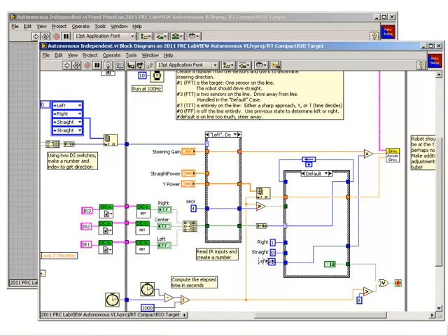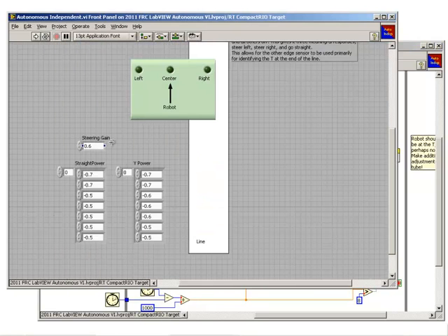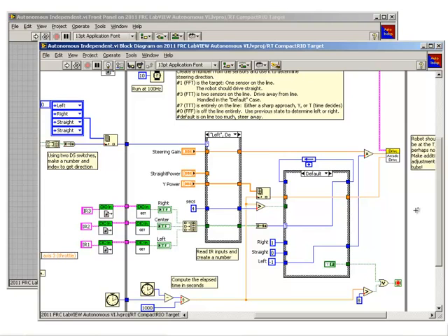Straight has a value of 0, therefore the robot will not turn at all. The degree of the turn will be determined by the value of the steering gain constant. A higher value will cause the robot to make a sharper turn, whereas a lower value will cause the robot to make a more gradual turn. To understand why the steering gain affects the robot's turning, think about how arcade drive works in teleop mode. The Y-axis, or pushing forward on the joystick, gives us speed, while the X-axis, or pushing right or left on the joystick, gives us steering. Keep that in mind when looking at the number being calculated and sent into the arcade drive function.